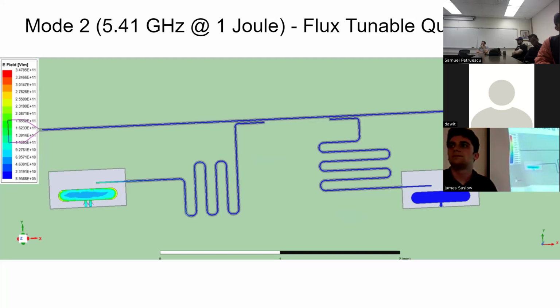So, yes, I understand there are modes, and how each circuit responds to these different mode frequencies. Do you have an S21 chart in this simulation showing that? I do have an S21 chart. I don't have one in this presentation. Okay, but where was that notch at? Was it in one of those frequencies or was it a different one? Yes, it's going to be in one of these frequencies. Whenever there's a transmission, you're going to see a spike in S21.